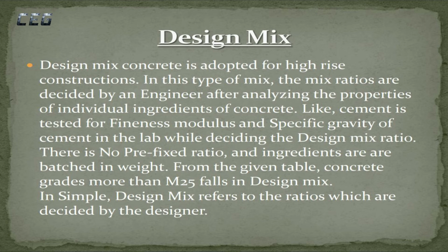While deciding the design mix ratio, there is no prefixed ratio, and ingredients are batched in weight. From the given table, concrete grades more than M25 fall in design mix. In simple terms, design mix refers to the ratios which are decided by the designer.